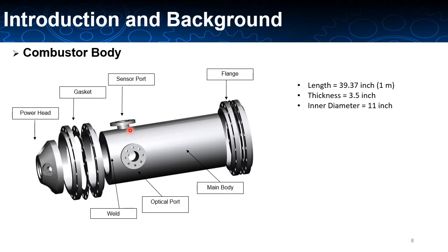Also, there are a couple of windows on the combustor body, and we can use those windows to actually look inside the combustor. And also we can use them to put sensor ports like thermocouples or pressure transducers to get the data.